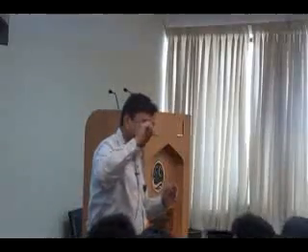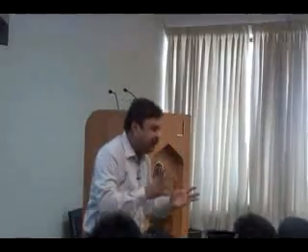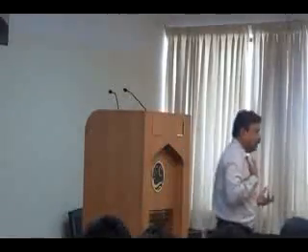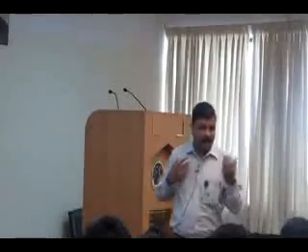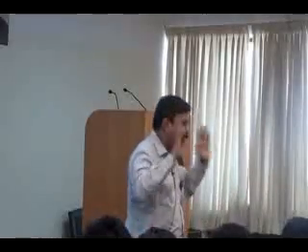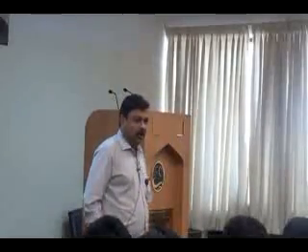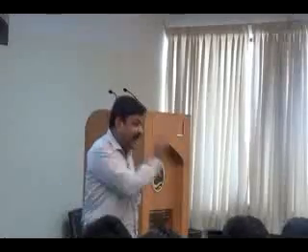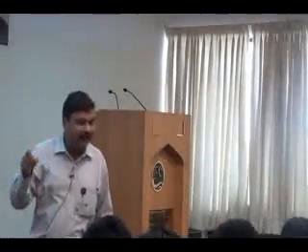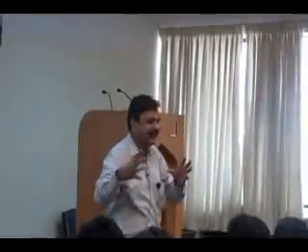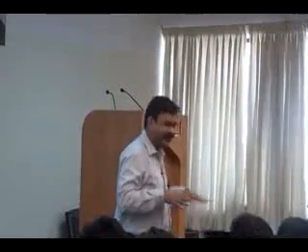Now, I want to apply a load, and at the same time it should deform easily. That means I have to look for a low Young's modulus material, which we colloquially term a soft material. Is it okay? So that is the material that I must go for while selecting my gripper. Are you able to trace the path, the voice of the customer takes? That is the objective of the exercise that I am doing today.